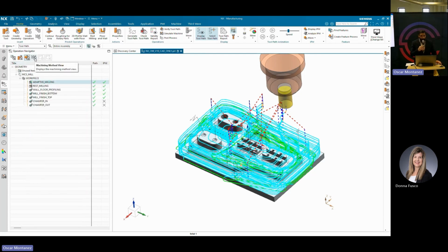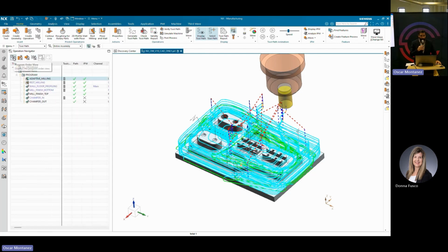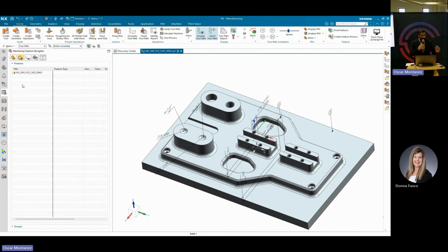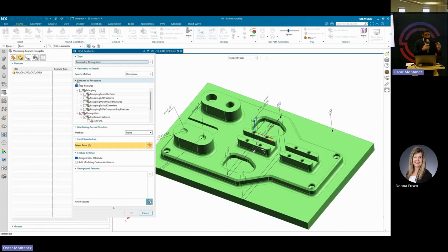If you choose not to save the tools in the template, you can let NX grab a tool from the existing library, and that's where your equations have to come in. If you don't have an equation set up to choose the appropriate tool, it'll just choose the largest diameter tool to produce that particular feature by default.